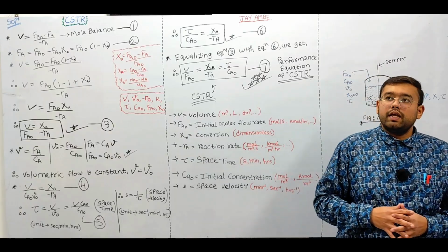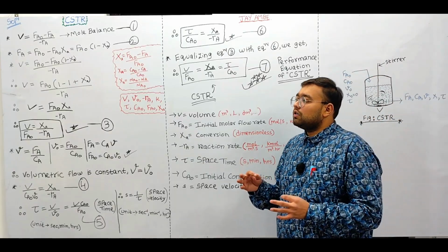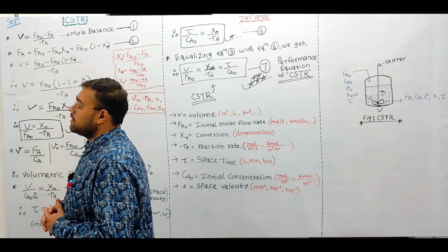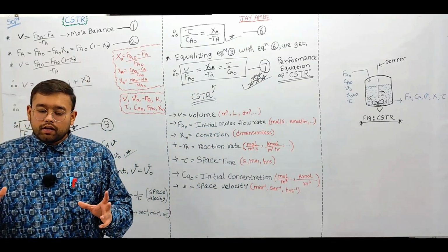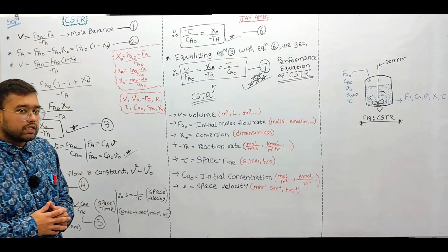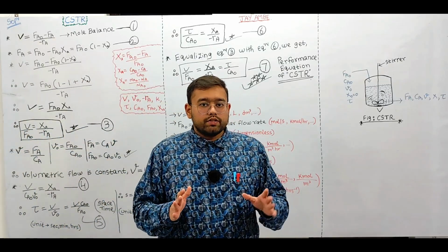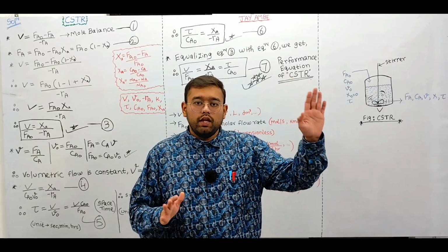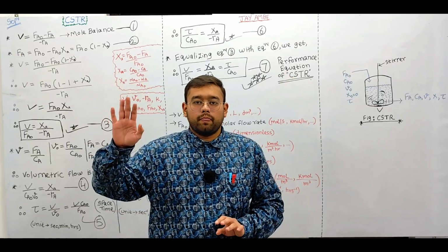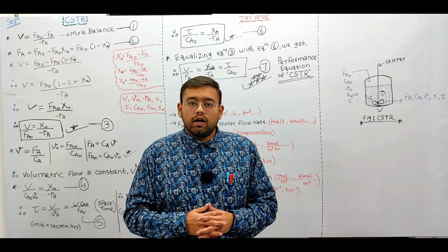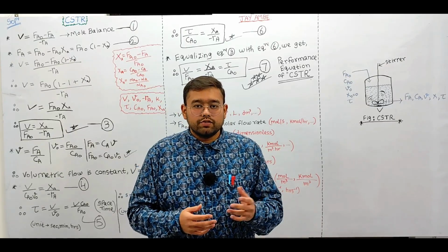The first question which arises in our mind is what the term performance equation means. The second question is what is the significance and importance of the performance equations, right? The performance equation is the equation which connects reaction kinetics with reactor design. In chemistry, we have studied how fast a reaction occurs, right?